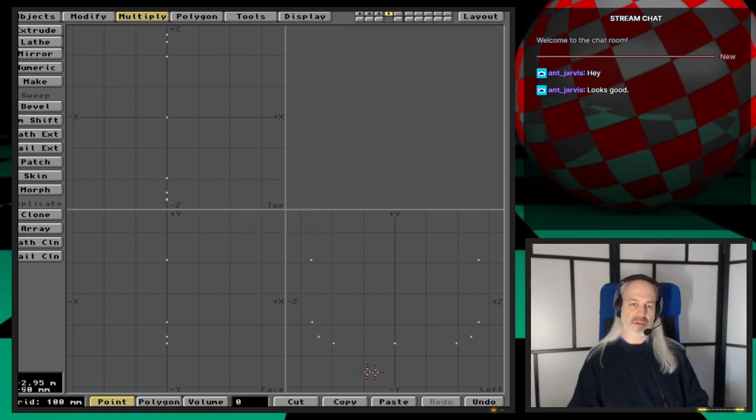And now what I want is, so that's what I'm trying to achieve, I want a smoother line here. Okay, so I'm going to be taking this, doing a curve, an open curve, make another open curve here. Great. Okay. Now I'm going to be selecting these curves, polygon, selecting these curves, and Control D for freezing them.